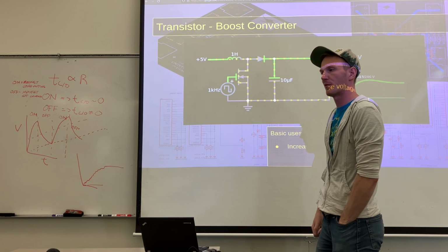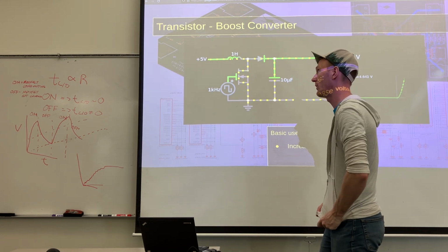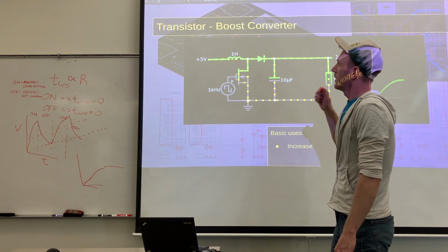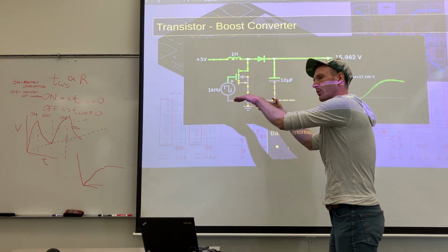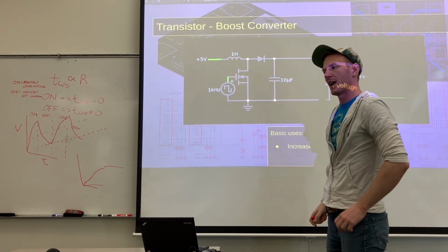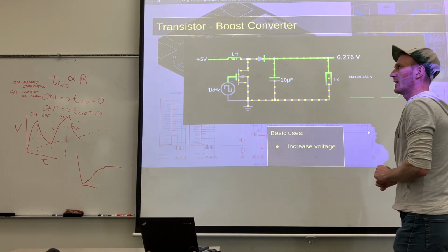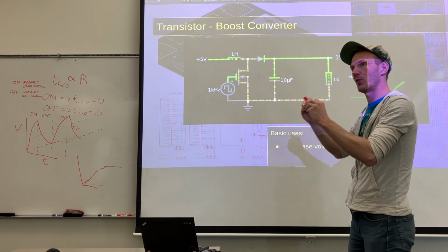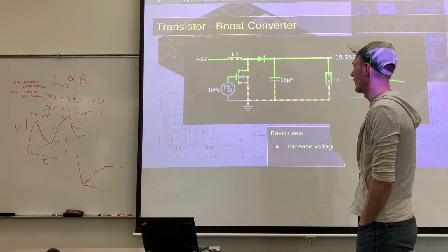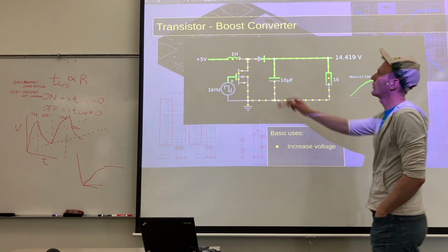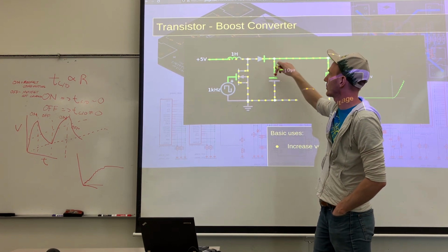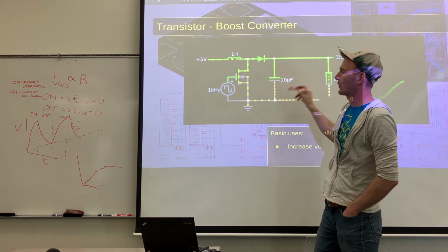Once you've built the field up, if you were using pure DC and not doing crazy stuff like we are, but because you allow it to build up this rapid field and then you stop it from going this way until it has a lower current that it wants to be at, it discharges its field because it cares about current more or less. So it wants to conserve its current. This diode is just here to make sure that when this is discharging, so in the on cycle, when this is shorting this way, you have a little bit of stored energy that's continuing to provide power.